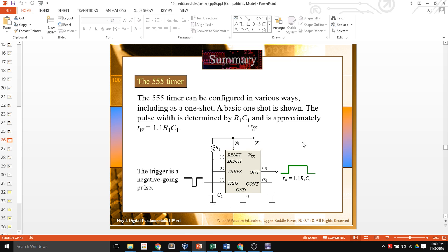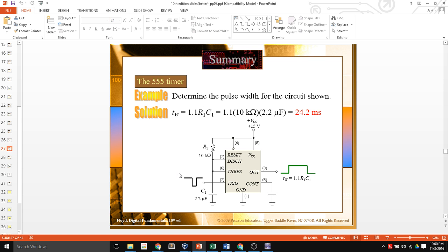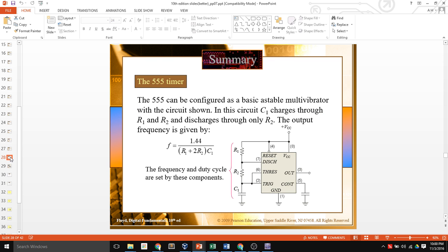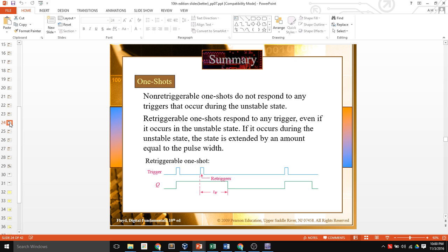Now, we can use a chip called the 555 timer to do that as well. And so that's a very interesting chip. We'll actually build a circuit with this in the lab next week. And we're going to build a circuit that does what's called astable, not monostable. So right now you can configure a 555 timer to do a one-shot or monostable output. You could also set it up to trigger what's called astable, where it continuously goes back and forth just like a clock signal, on, off, on, off, on, off, at a predictable rate of time. And so we can actually design that and build that in lab.